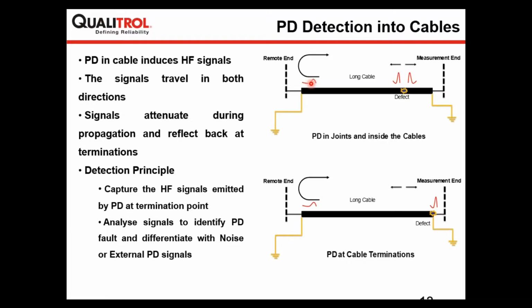So the idea of detection of partial discharges is to have the sensor on the cable earth shield, and it will be detecting partial discharges which are traveling along the length of the power cable. Whenever partial discharges travel along the length of the power cable, they get attenuated. If you are measuring partial discharges, up to 5 kilometers you can measure them. If there is no middle grounding, you can detect partial discharges while staying at the end of the power cable.